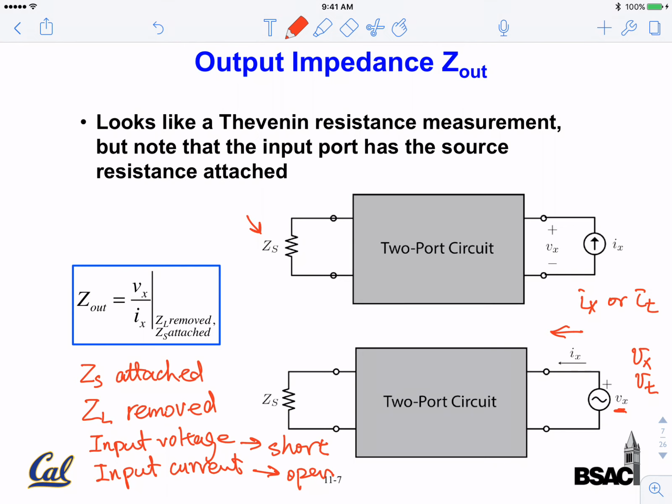We're going to practice this many times today. Questions so far? Yep. ZS is the resistance of the source, right? Resistance of the source. And the Z implies it's complex. Sometimes the source has capacitance. And capacitance, as you are experiencing now in your lab, will impose a frequency limit. So to generalize that, the source resistance can become complex and become an impedance.